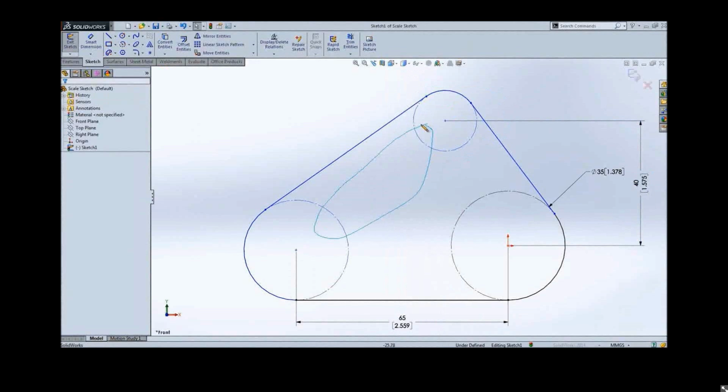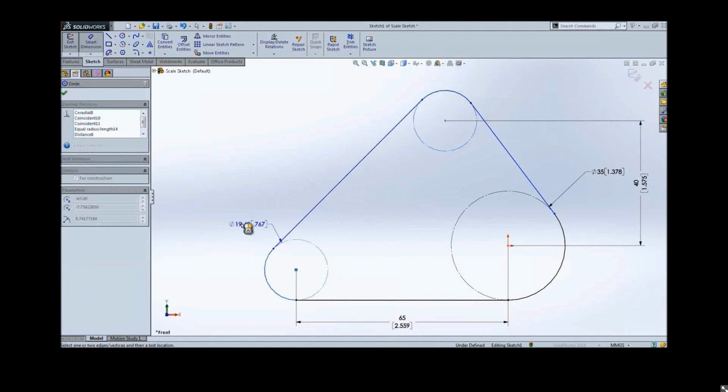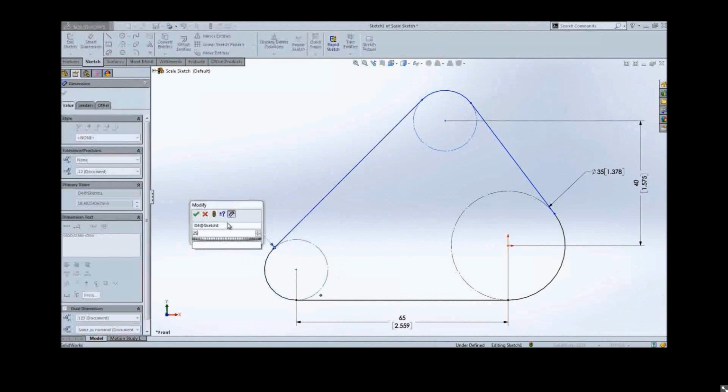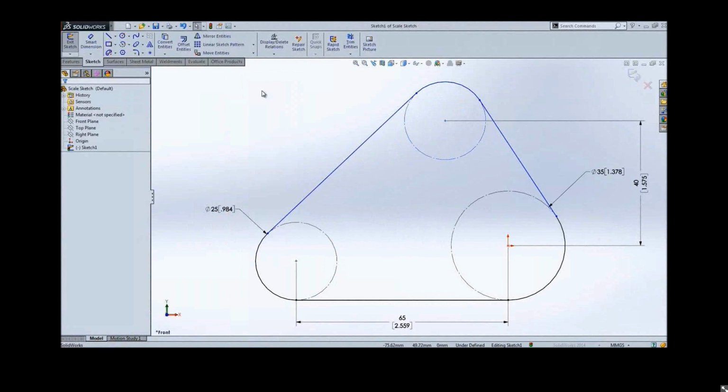So it's really nice that we're able to do this in SolidWorks now. It also incorporates the left to right and right to left selection methods, the same as the box, where right to left would only select every entity which has been crossed over, and the other one would select everything. So it really makes it fast and easy. Again, I can select these two circles here in this belt drive system without actually selecting the belt around it. So it's nice to pick and choose which entities we want to scribble over with that.